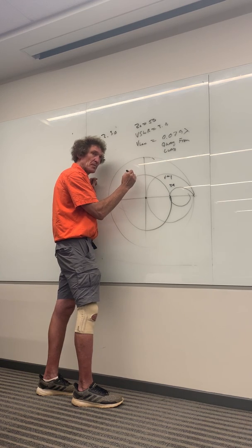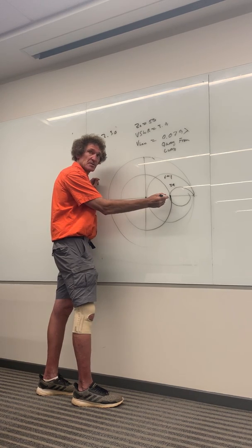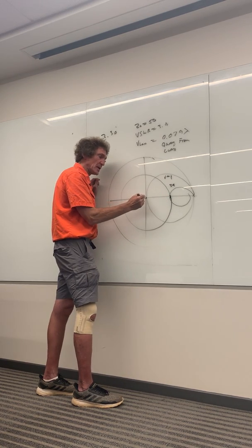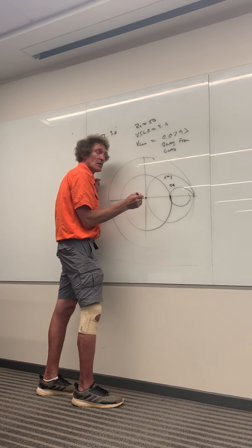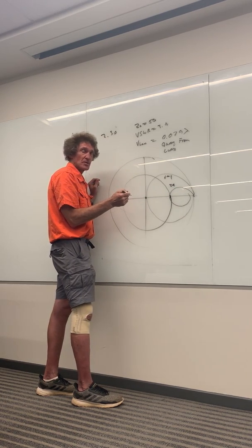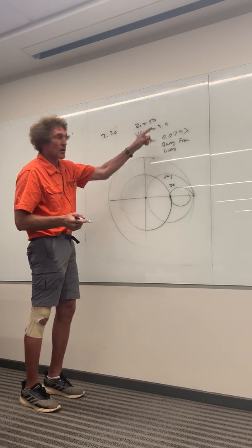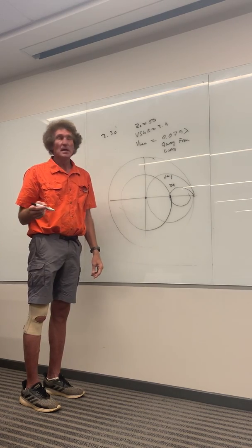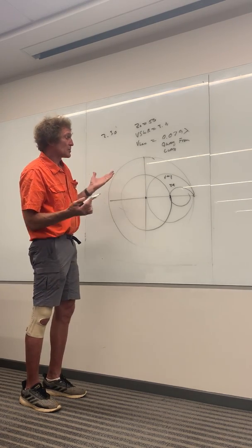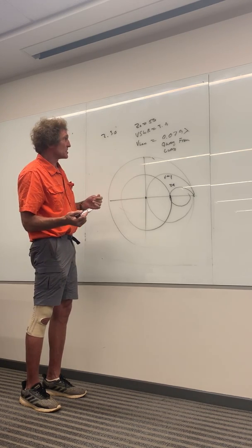The reason I say this is I know when you plot Z load normalized, wherever it is, and you move, the Vmax occurs at the intersection between this 0 point and the infinity point, where the value is greater than 1. So you're going to see something of 3.4, and that is your VSWR. You follow me on that, class? Everybody got that? We covered that last time. So now we know the radius of the circle, that's the bottom line. The radius is the magnitude of the reflection coefficient.